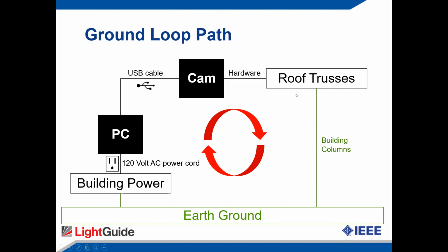And I think these were USB 2.0 cables, so they weren't even necessarily very high frequency, 480 megabit per second. It's a USB 2.0 data rate as opposed to 3.0, which is 5 gigabit, which would be even more sensitive, I think, to interference. But certainly, if you have a ground loop, your earth shield ground on your USB cable no longer helps.